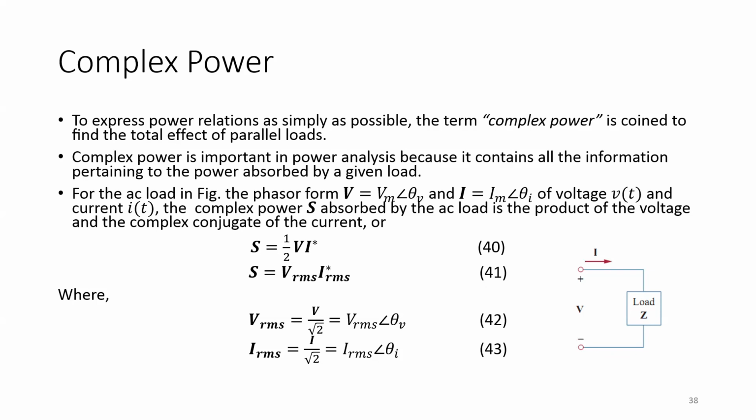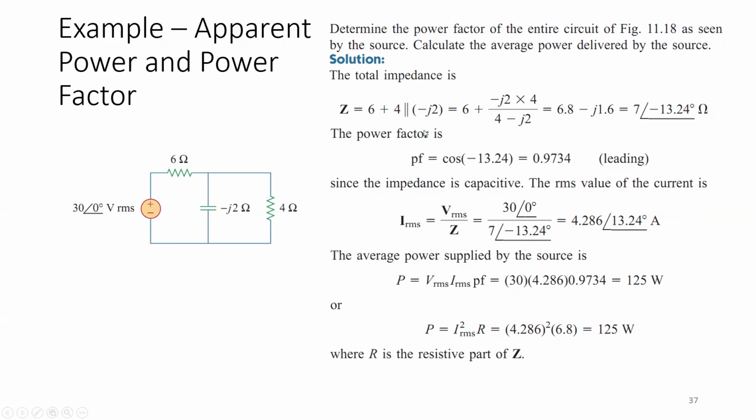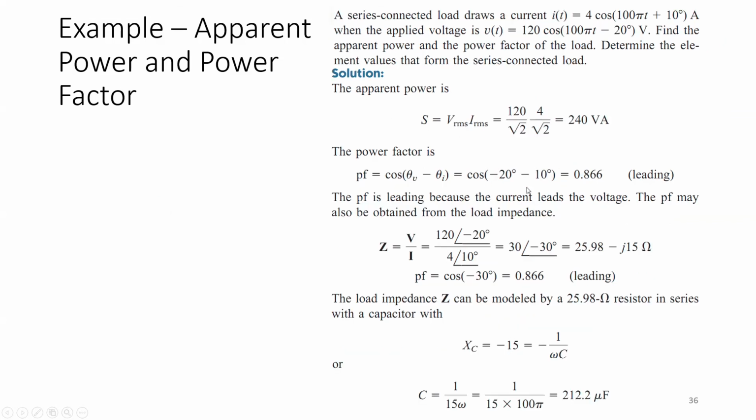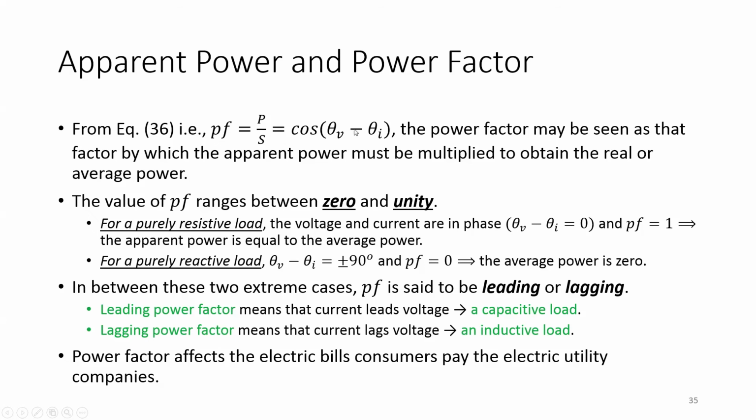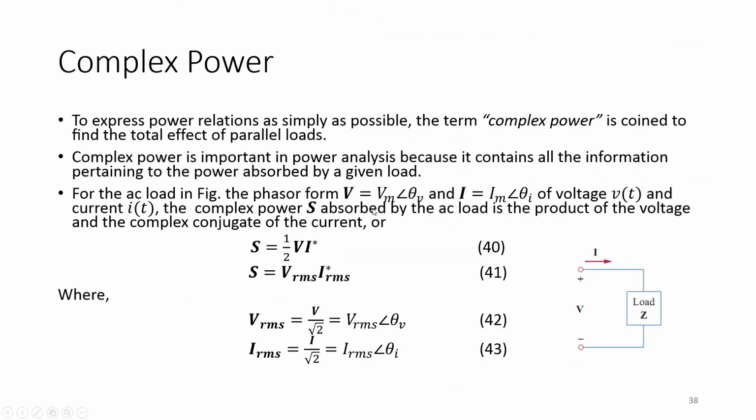It is the product of the voltage and the conjugate of the current through some element, and this conjugate on the current is nothing but to indicate the negative sign we have been seeing constantly in our previous calculations, like the one in the power factor angle. This is for mathematical reasons, there is nothing else hidden in it.